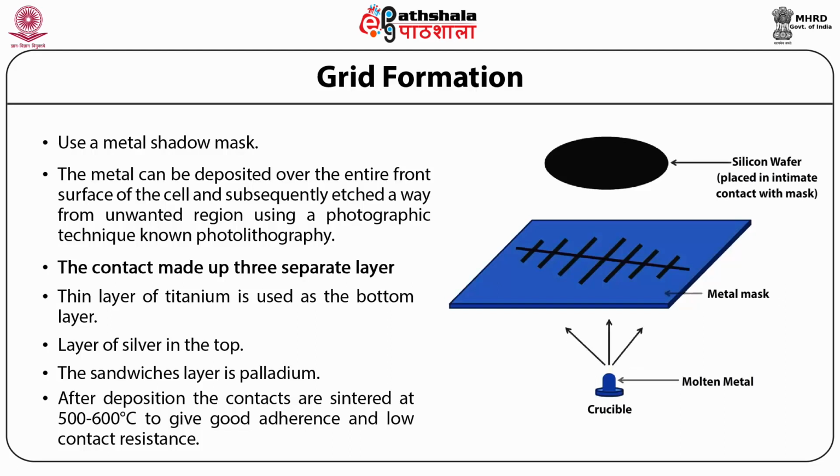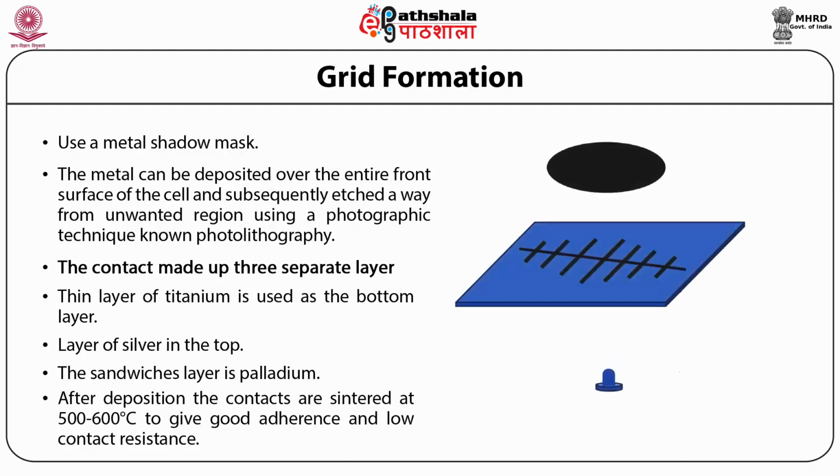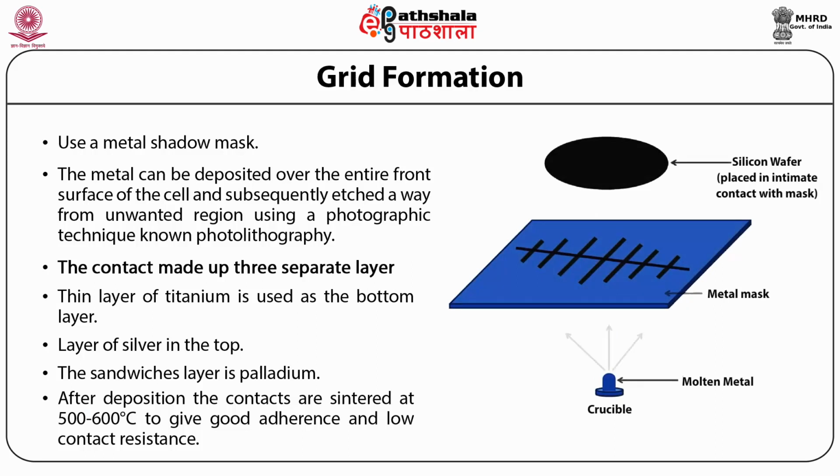However, it is expensive as it is a batch process, and also it includes the expensive materials. Hence, now here the silver paste is used for the front metal contact and the aluminium paste for the back metal contact. The equipment used in this process is inexpensive, easy to maintain, and a mask can also be done on the solar cell surface.